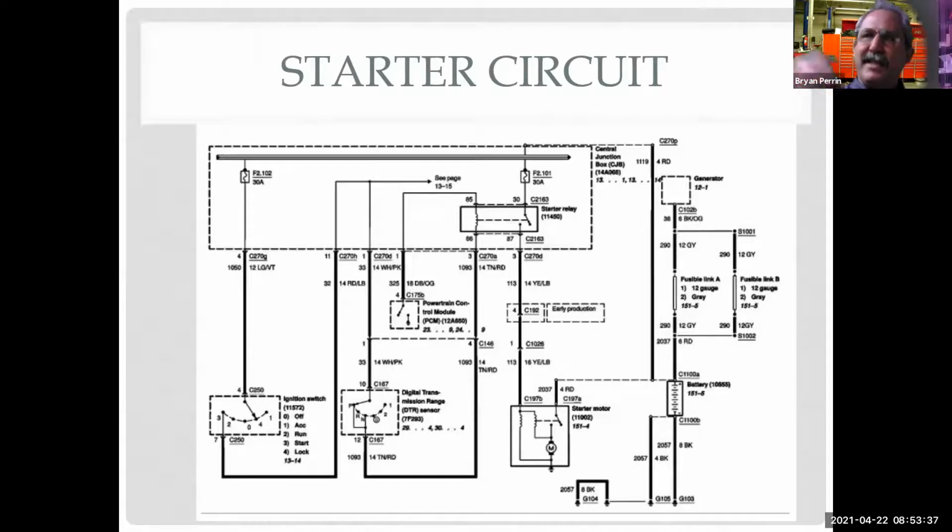So it can disengage the starter sooner, less drag on the engine, it's going to start quicker, the starter lasts longer. So the key point is not so much making the starter last longer, but it's lowering cold start emissions is why they do it. Almost everything on a car is about emissions. So they really don't care that your starter lasts for 400,000 miles instead of 40 like they used to. That's really not the manufacturer's goal. The manufacturer's goal, the reason why we have this technology, it really comes down to emissions, right?